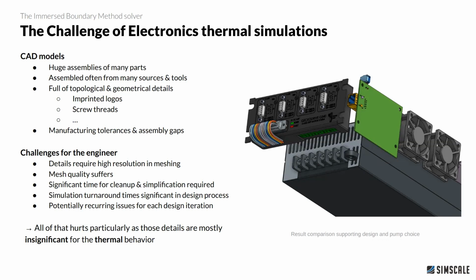So I already started mentioning the challenges for the engineer. So these details require a high resolution in meshing to be even resolved, but they also need an even higher resolution to get acceptable mesh quality. And the mesh quality is quite important for your simulation to converge and actually be stable and successful.